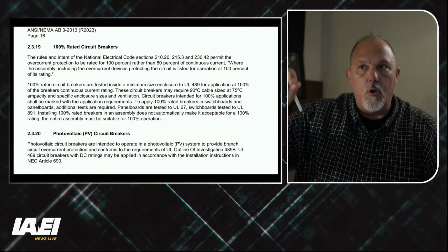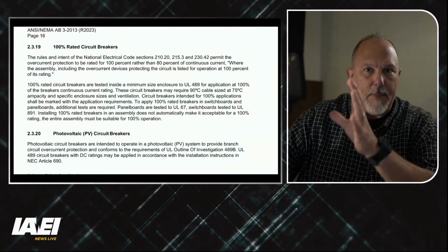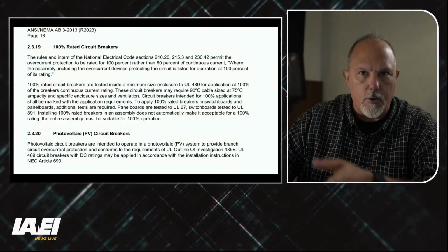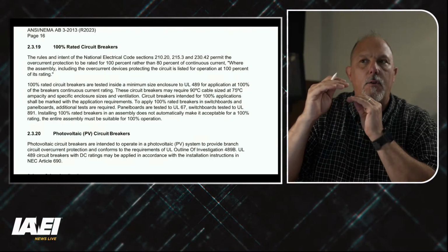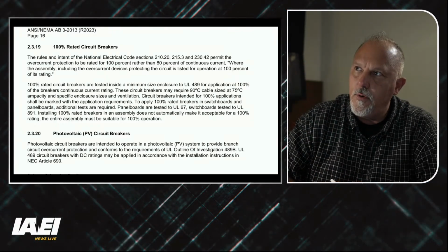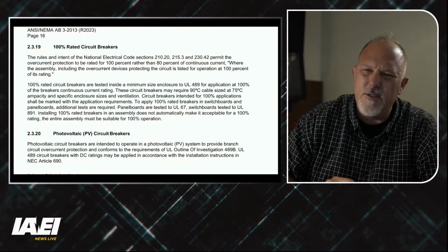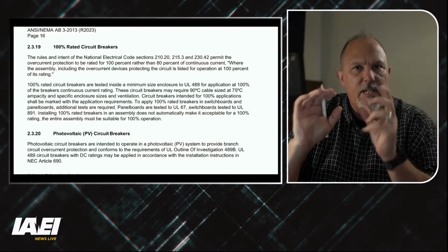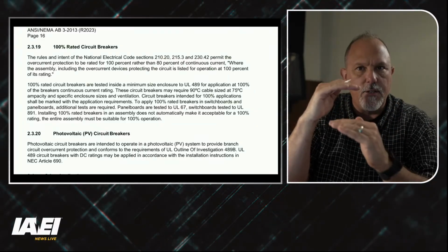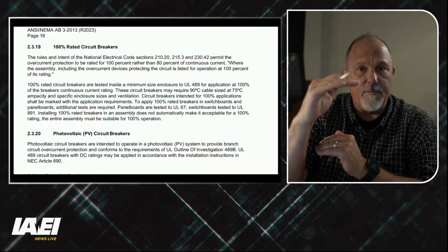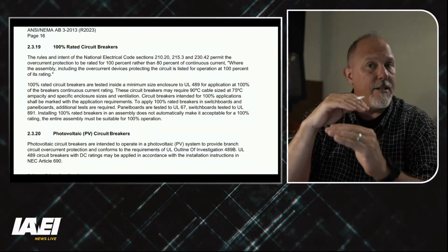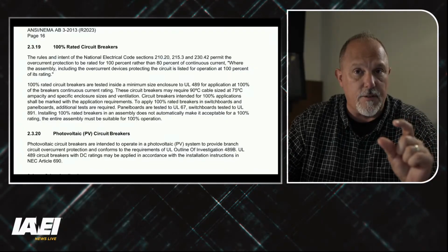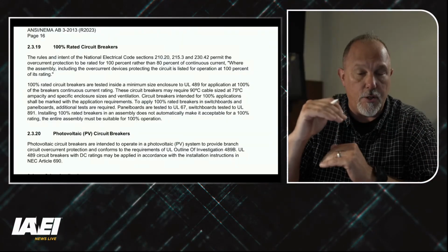And if you recall, when we do an ampacity discussion, whether it be Article 215 or Article 210, I think it's 215.2 and 210.20, somewhere in there, they'll tell you that you have to do two calculations, one at 125% times the continuous, the other with just the conditions of use. You pick the larger of the two.